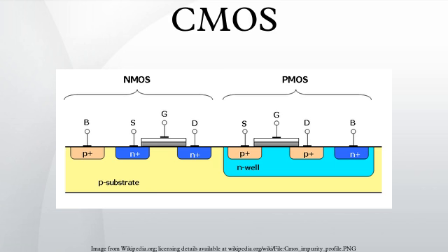Since most gates do not switch at every clock cycle, they are often accompanied by a factor called the activity factor. Now, the dynamic power dissipation may be rewritten with this factor. A clock in a system has an activity factor of 1, since it rises and falls every cycle. Most data has an activity factor of 0.1. If the correct load capacitance is estimated on a node together with its activity factor, the dynamic power dissipation at that node can be calculated effectively.